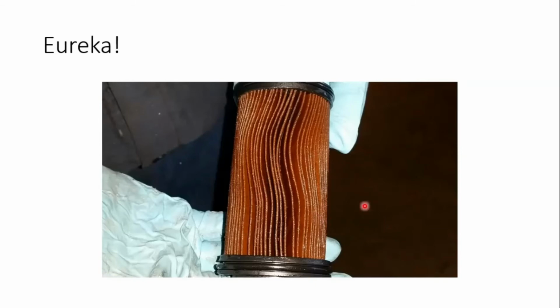Here's one of them right here. The filter was causing this issue. And I know what everyone's going to say, Mike, you got to be kidding me. It's true. The filter element had gotten all squishy, and basically what it was doing, it was causing a restriction, and that was making the pressure go down just a little bit, get all hashy.